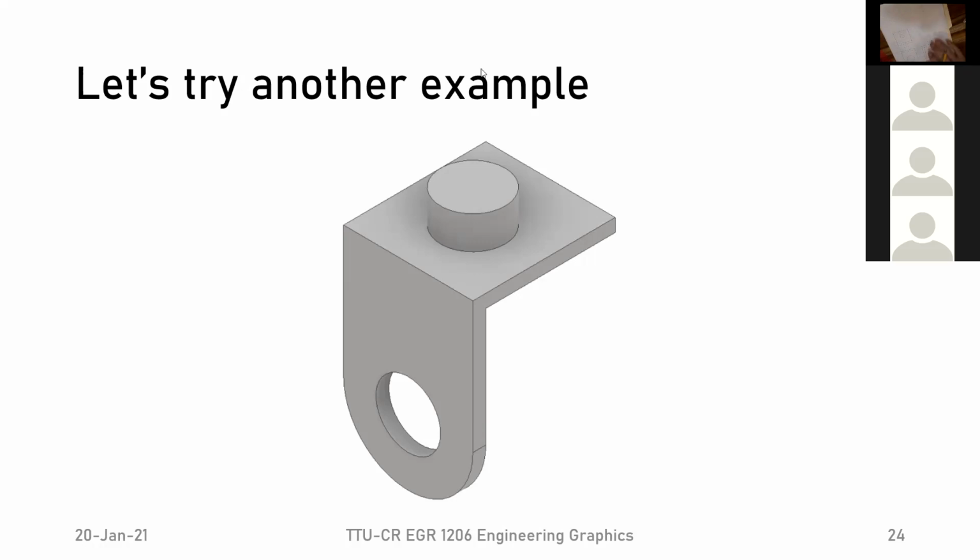Because we have circles. So now what do we do? Where do we start? Well, let's start with our big one right here. So we have this big circle. Usually we want to have our center lines go all the way to the edge of the circle that they're for. In our case, the center here is a center for two circles, the small circle and this half circle right here. So we have to extend it all the way out there. So we'll do a smaller dash in the middle, halfway straight, and then a longer dash all the way out across where this is. All the way out like that.